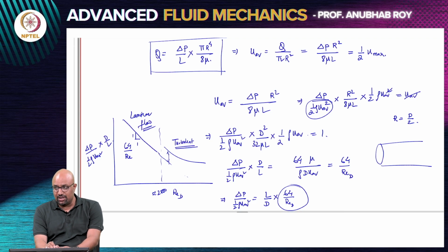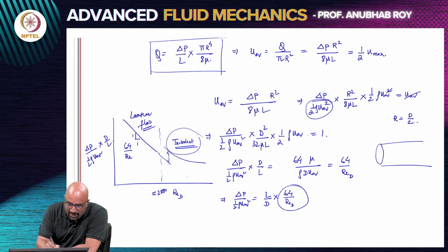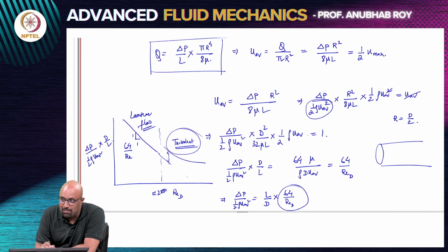All the assumptions that you have made in the problem of steady, fully developed, axisymmetric, no swirl, if not all, most of them actually break down, and you end up getting a flow that is highly three-dimensional, unsteady, and there is a significant amount of components in other directions. So, with this you arrive at what would be a turbulent flow where the pressure drop is much higher.